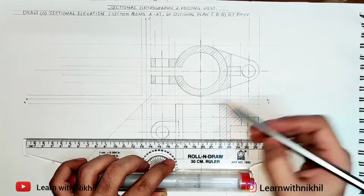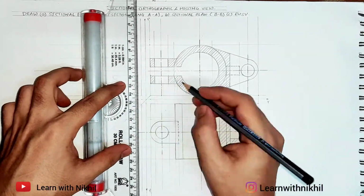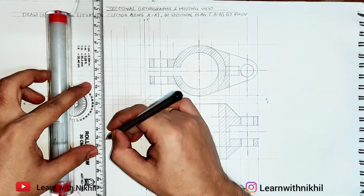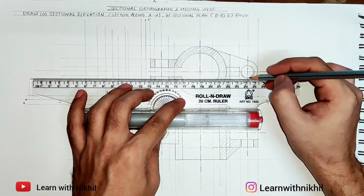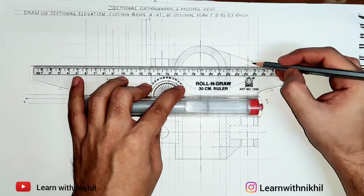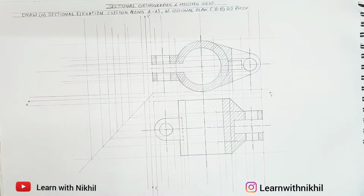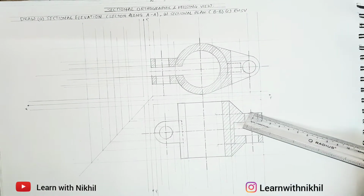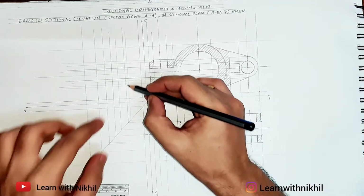Now taking the projections, all the projections from the top view to the 45-degree angle line, from the 45-degree line upwards towards the right hand side view, and then from the front view to the right hand side view. Now to start with the side view, from this direction we'll see the side view. So first part will be visible, that is this part. So I locate this part.